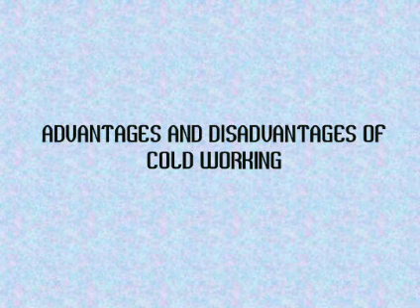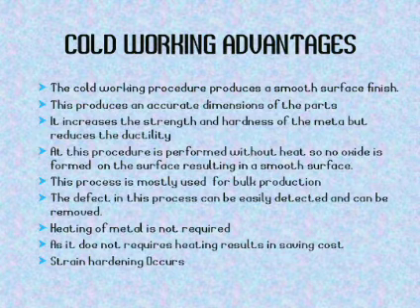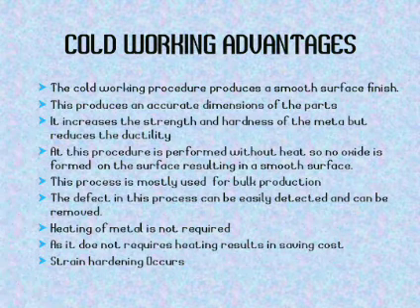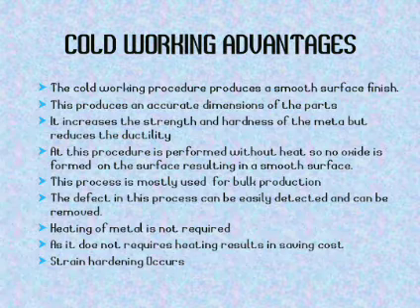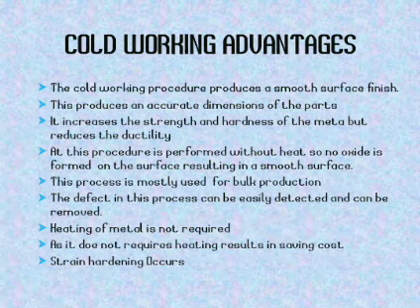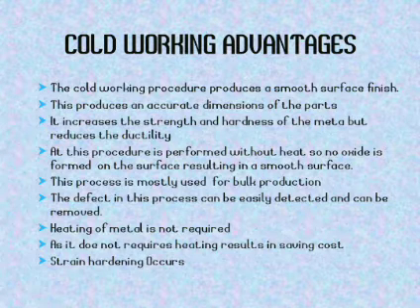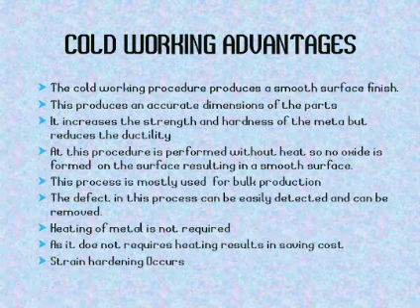So we will have the advantages and the disadvantages of cold working. First, we will discuss cold working advantages. The cold working procedure produces a smooth surface finish. This produces accurate dimensions of the parts. It increases the strength and hardness of the metal but reduces the ductility.